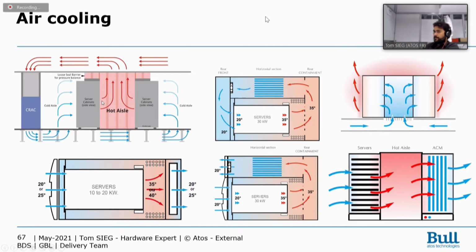And the last solution, it's almost funny, you have one row with your server cabinets and another row with your heat exchanger, and you will be able to put a cabinet just to have 2 cold corridors and 1 hot corridor. All these solutions are to optimize your air system and to make it more efficient.